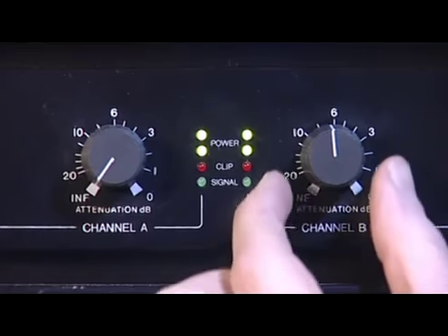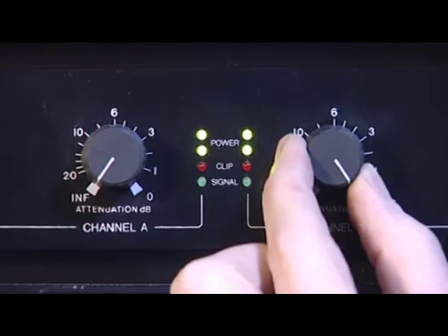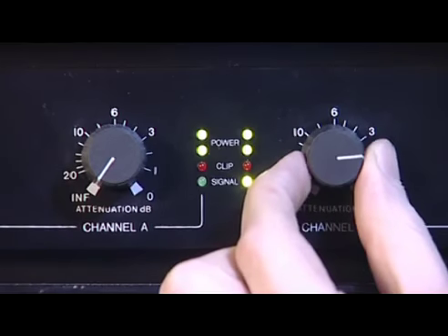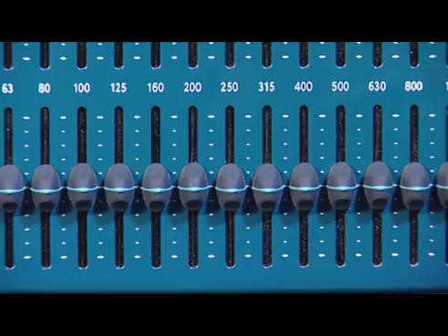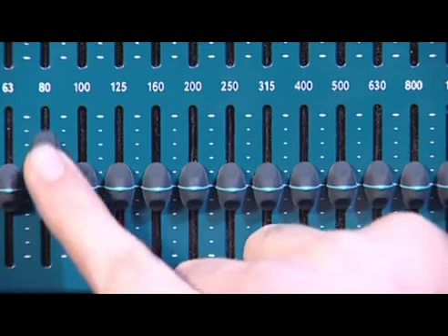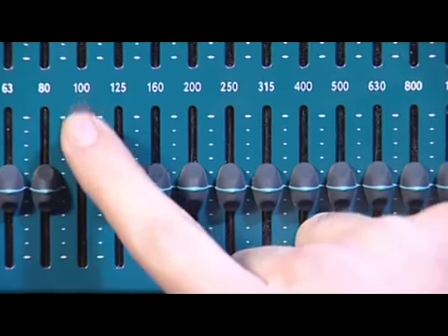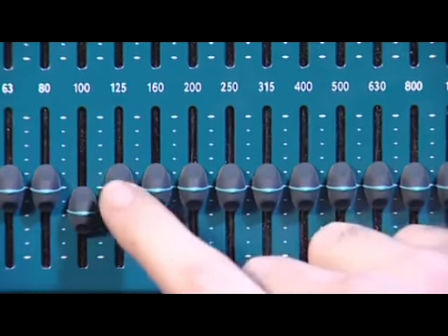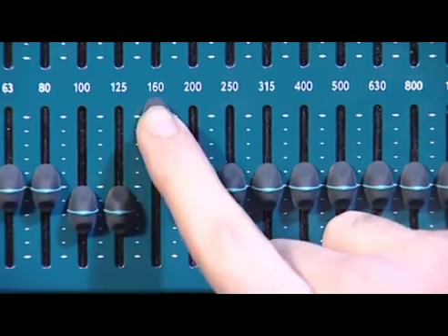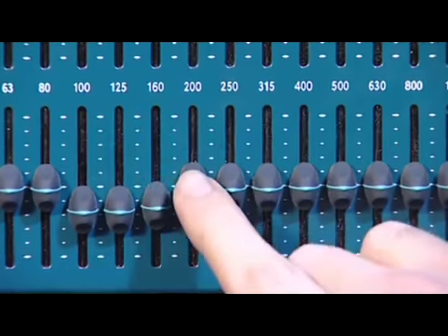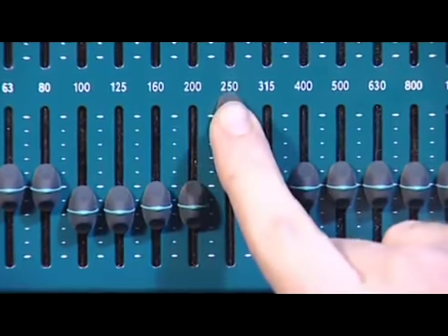Turn up the amplifier volume until you can just hear the sound start to ring. Turn back the volume slightly so that the ringing doesn't turn into feedback. Starting from the left, adjust the first graphic EQ control to maximum. If the system doesn't feed back, then this isn't a problem frequency, so put the control back to 0. If you do get feedback, reduce the gain at that frequency. Do this again for all the other frequencies on the equalizer.